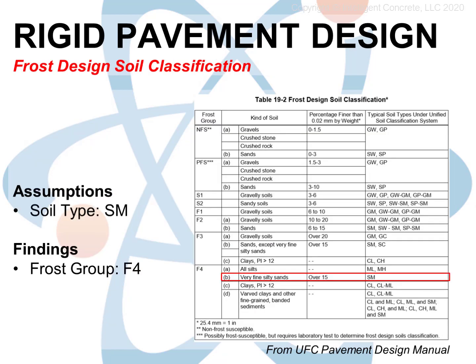I promised we'd get to this. Another component of pavement design is whether or not we must account for frost. In most parts of Colorado, we do. At the Air Force Academy, we do for sure. Frost can affect structures because frozen soil, if it contains too much moisture, will heave or swell. It may not seem like it would be that much, but the swelling pressure is intense, about 30,000 psi, with 5 to 9% expansion of the water, and it's capable of splitting solid granite rocks.